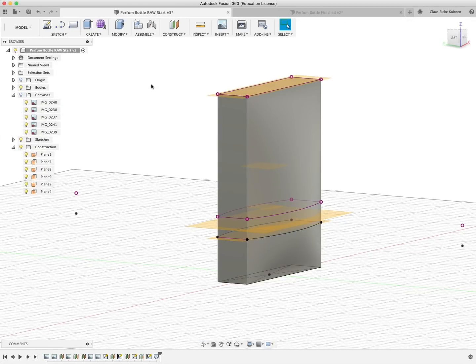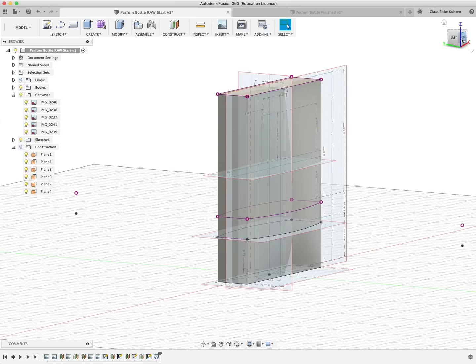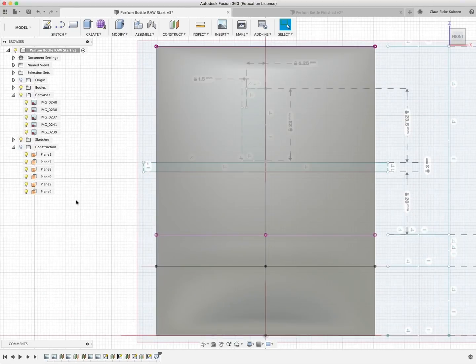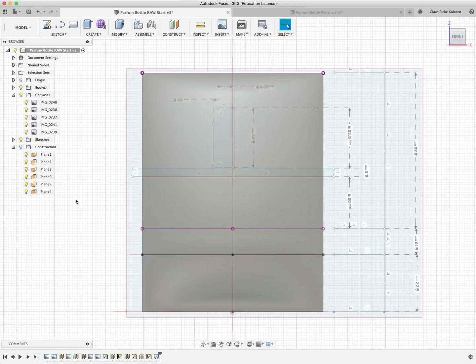Something with parametric modeling where you have to be very careful about is the correct step-by-step order. When do you do what? So later your construction tree in whatever program you use is very easy to read, and when you want to modify your design, it is also easy to adjust these features. So there's a little bit of pre-planning and art involved to it.